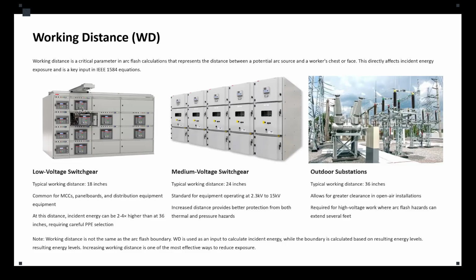In fact, for a given system, doubling the working distance can cut the incident energy by a factor of 4, depending on the enclosure type. So choosing the right working distance is not just about the math, it's about modeling realistic human exposure.